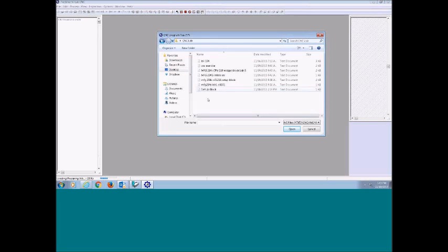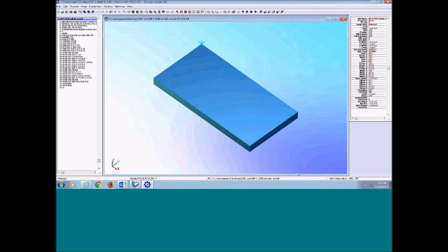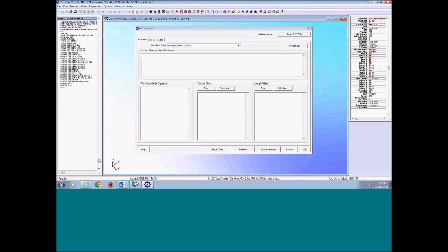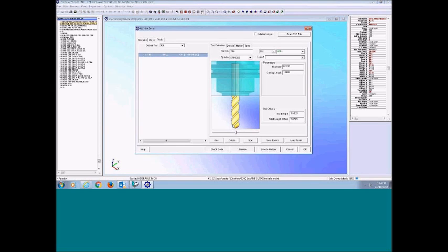Okay, these are various, I'm going to show you some of these next week. But if I go to the initials, I hit initials and say open. All right, and I'll say okay, that gives you an opportunity. This is what you set up. I'm just briefly going to show it to you, but I can go to File, Job Properties, and this is where I set the machine up, I set the stock size up, and I set my tools up in my program. And I'll guarantee you, if you're wrong, it's going to let you know it will not run.